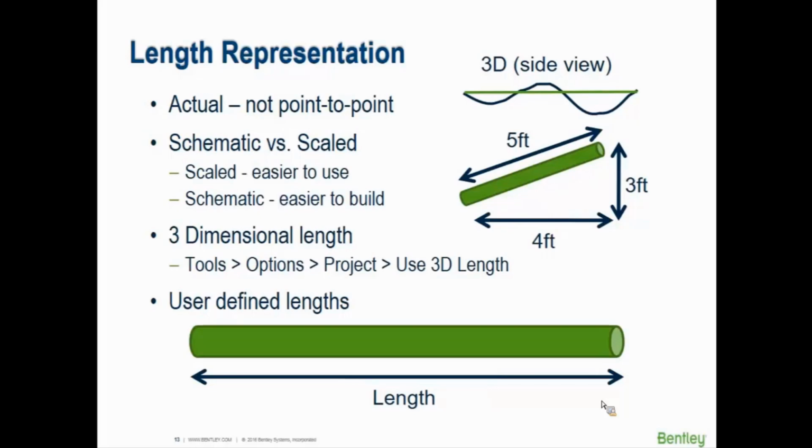If you messed up any of the elevations, it's really going to show, meaning it's really going to make a big difference. Whereas if you have that messed up elevation somewhere, just in plan view length of pipe, it's not going to be that big of a deal. So if you choose to use 3D length, just double check and make sure that your elevations on your nodes are right, so you don't have some super long pipe going down to 0 elevation.